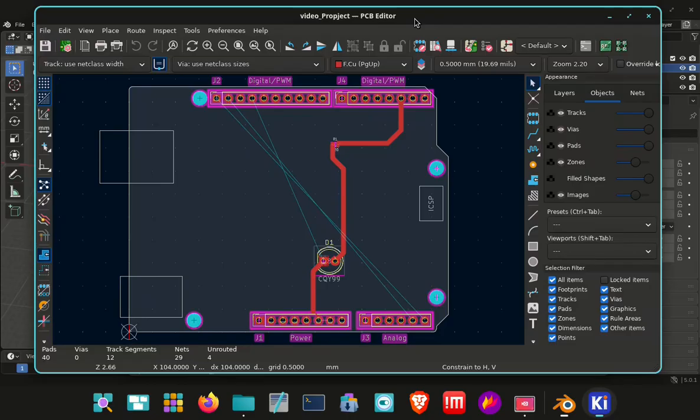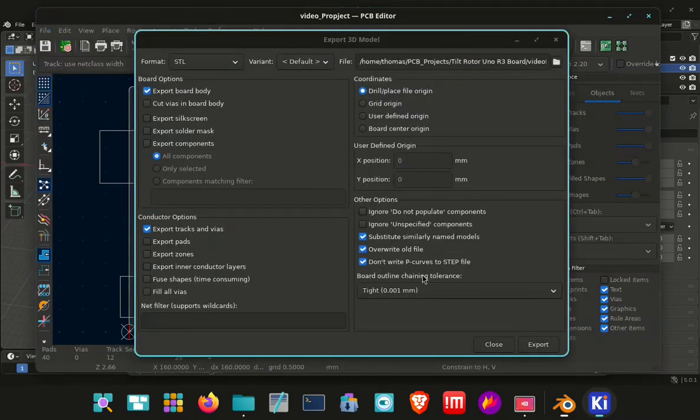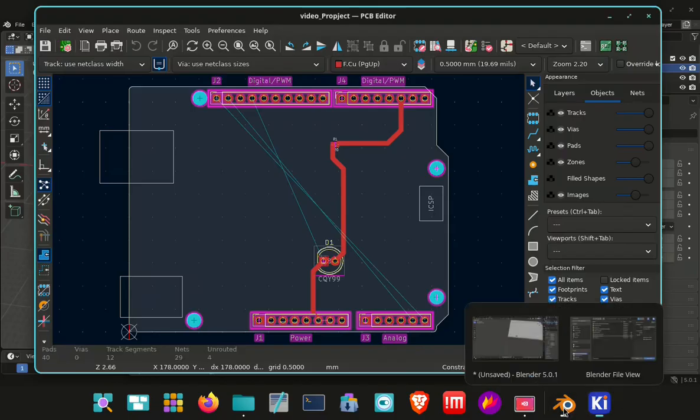So you're in this window and you're stepping forward to export. If you leave this window open, because it's waiting for you to finish this function and close this manually before it will do anything else. So if you find that KiCad isn't responsive, just make sure you haven't got any windows open.